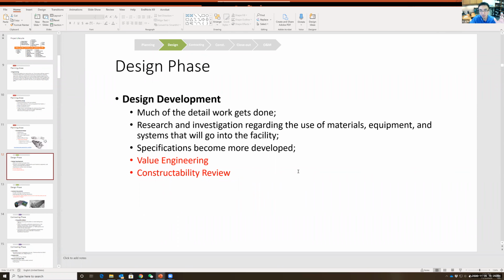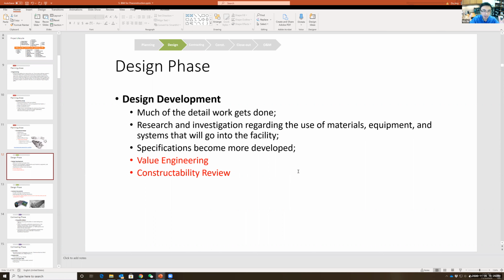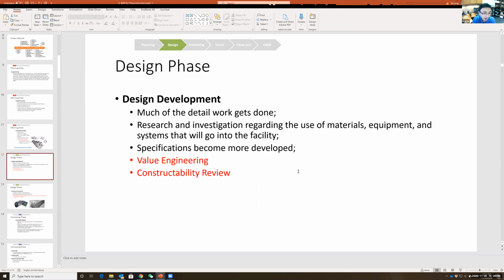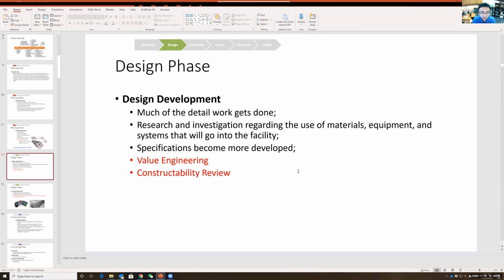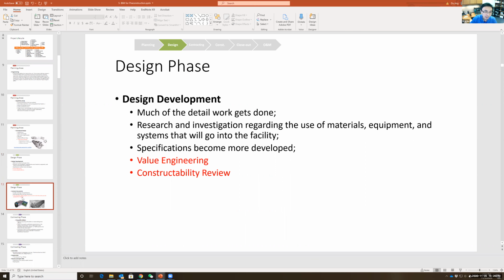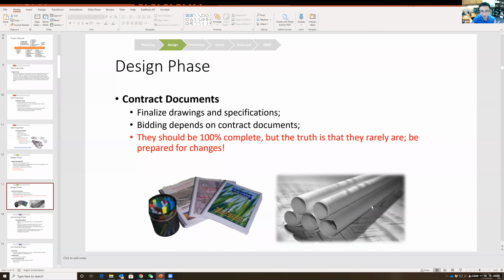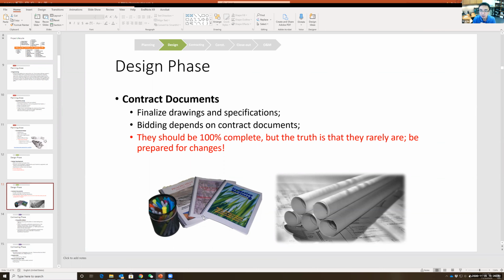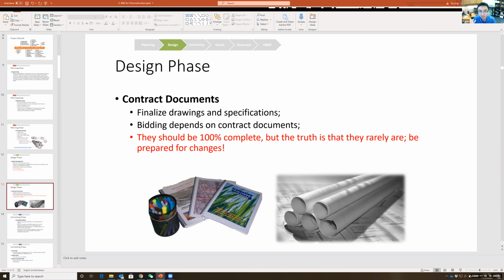Design development is around 50% done. You start to see some structural information, more information about architectural features. And then we have the CD, construction documents. So you have complete details such as the rebars, the schedules of materials, the doors, the windows, all the detail. That's the entire design process. And the deliverables would be what? Specifications and drawings, the two deliverables. One is the written material showing the materials and workmanship requirements, and drawings are the visualized way of showing pretty much the same information.